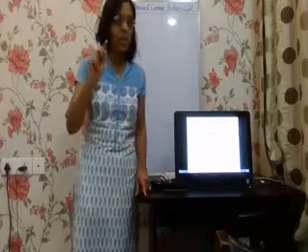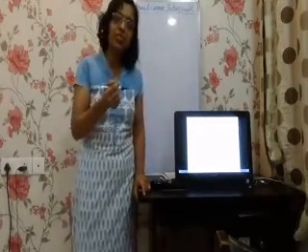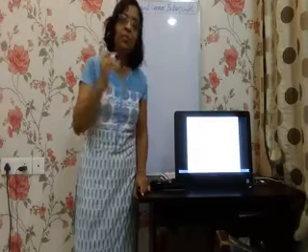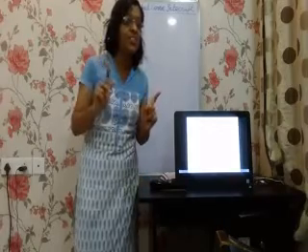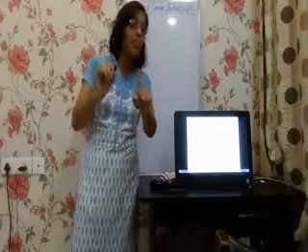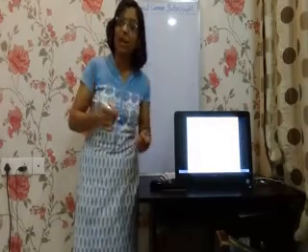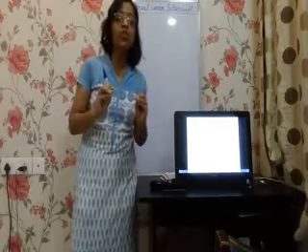Similarly, the RI flag. Whenever the 8051 acts as a receiver, RI is also 0 initially. When the 8051 receives the data bit by bit, it is deframed and stored in the SBUF register again. When 1 byte is completely received, the RI flag is set, indicating that 1 byte is received. It should be picked up and saved at a particular place before losing the data.